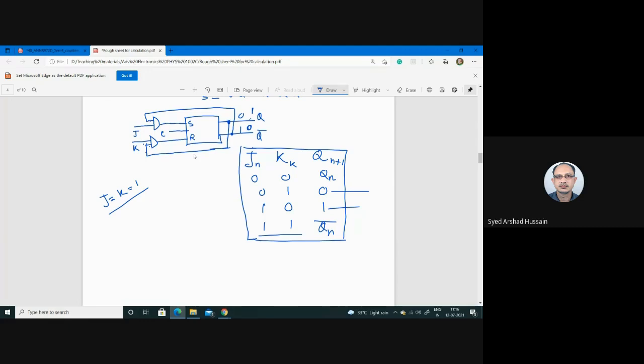So as long as your input, say this is your input pulse, the duration of your 1, say this is your pulse width, then what will happen? Up to this time period we have given 1, that means up to this time we have kept 1. So if during this time period the output changes and it can come to the input, then automatically the output will change again.